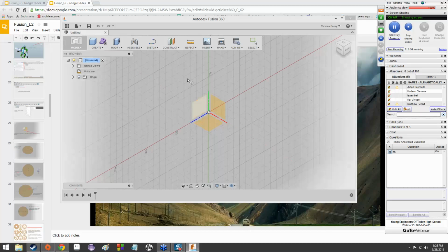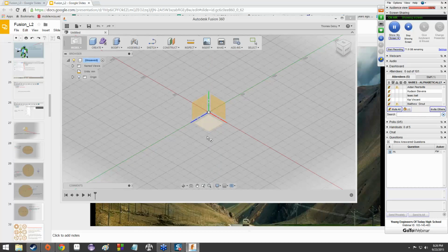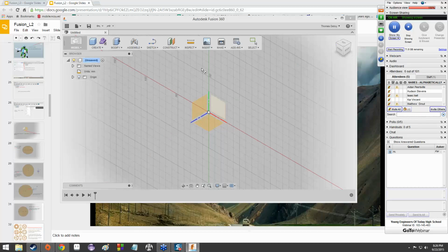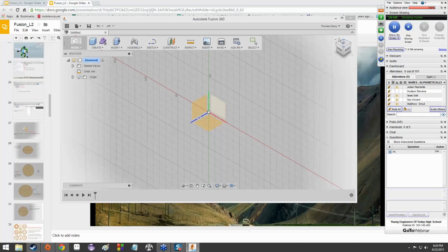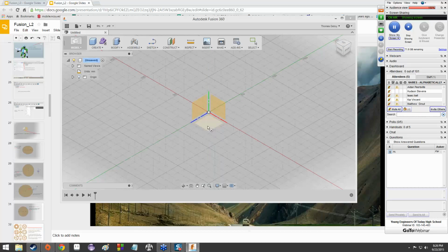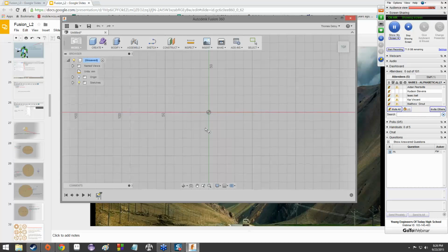So now it's going to ask us which plane we want to draw on. You remember this from doing the cube? I'm sure you do. We're going to start by drawing on the top plane. And if you remember, that's the bottom one, confusingly. But the easiest way to remember is that this plane is parallel to the top plane on the cube, and that's the best way to remember it. I guess, because it's also parallel to the bottom plane. But anyway, click on that one.